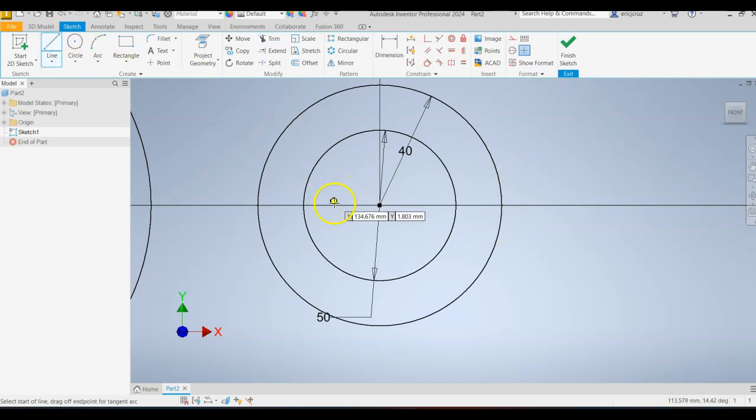Click line tool. You know what? You don't need the line in the middle here. I just realized that. Draw a line here, press escape. Spacebar will turn on the last tool you used, so that's what I pressed. Or you can just click line again. Draw another horizontal line. And dimension. So click that line, the center, move outwards. That should be 10. Repeat here.